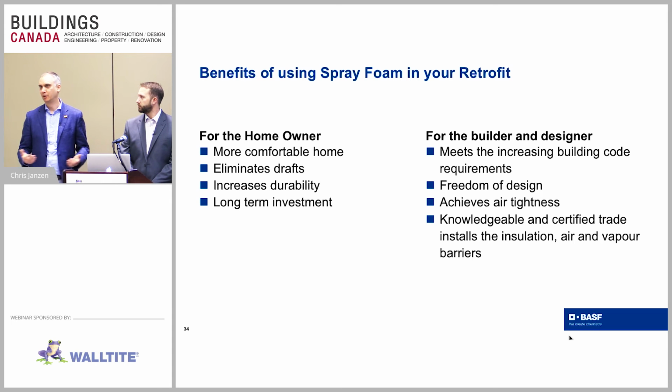And it gives you freedom of design as well. If you're doing additions with curved architecture or something like that, then the spray foam is very versatile. It's going to stick to most components in the building envelope that's typically used, and it's going to get that insulation in there. And again, the air tightness, we've been hitting home on that quite a bit. The R value is one thing, but the foam gives it that air tightness.